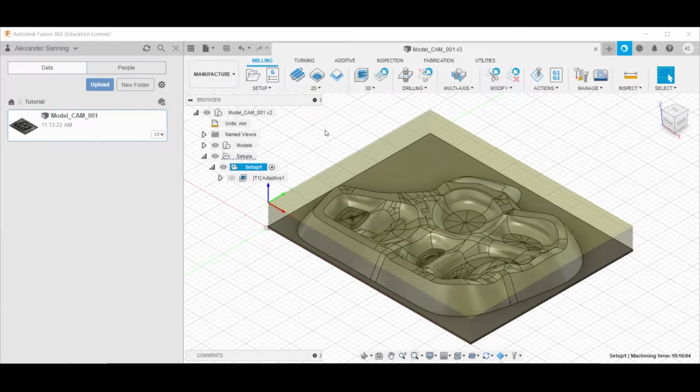One thing that we have to take into account milling plywood is that plywood when milled leads very easily to fraying edges. Since it is not a solid wood, there are very thin layers where each individual layer may deteriorate. Thus, it is important for us in this example, milling plywood, that we use a downcut tool.